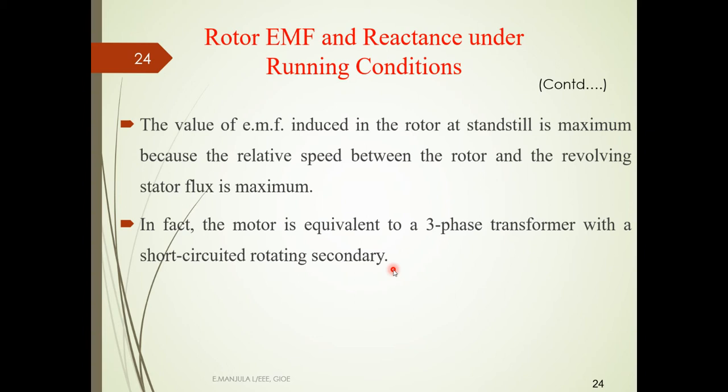Here, what is happening? In an induction motor, the rotor bars are short-circuited. So the winding of the rotor, we are short-circuiting it for self-starting. In the same way, when we take an induction motor, it resembles a transformer, where the primary is as such and the secondary winding is short-circuited.